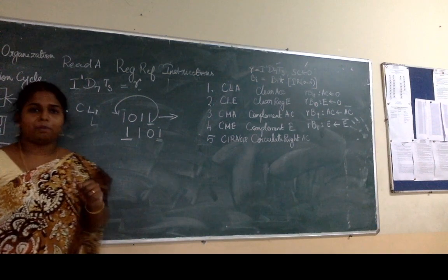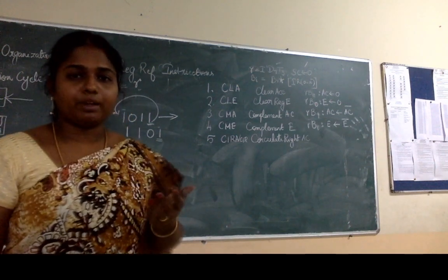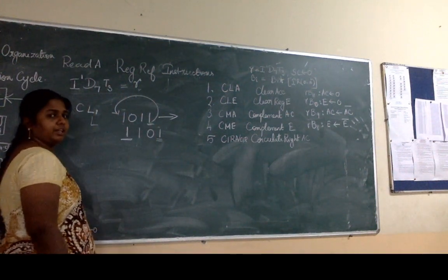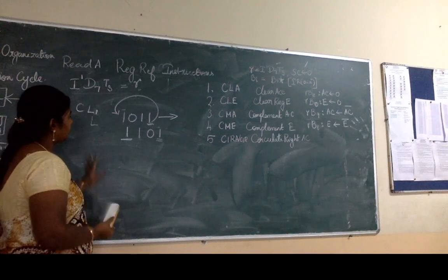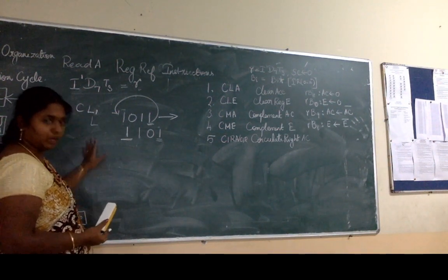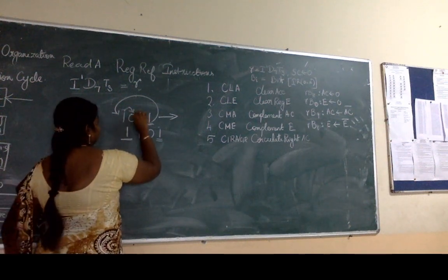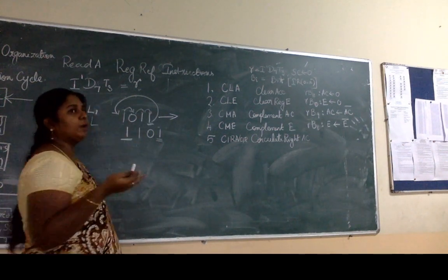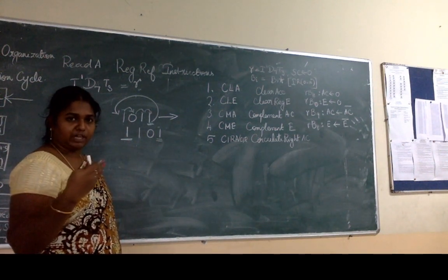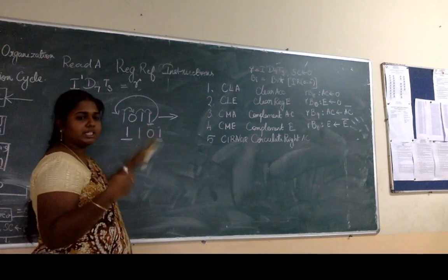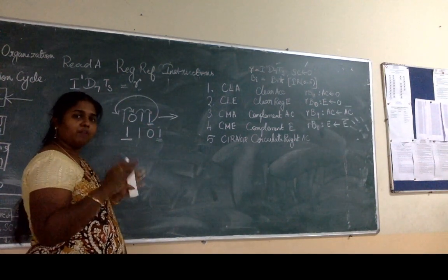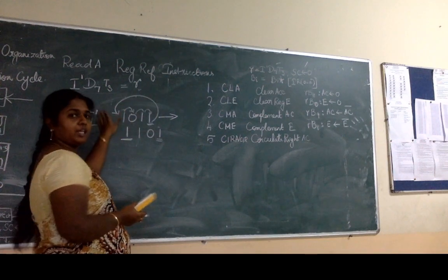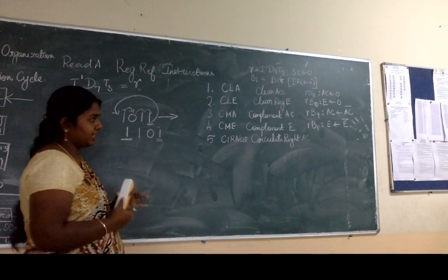Now to perform this operation, I need some temporary register where I can store this value. Right? When I just move them right by one position, if I write this bit here, this bit here, this bit here, one of the bits will be overwritten. To avoid overwriting of that LSB, I have to save this LSB to some place and then perform the circulate operation. Bring this LSB from the temporary place into the MSB. That's how the operation is done.